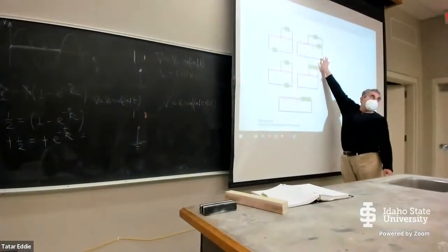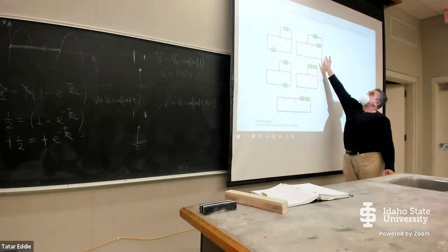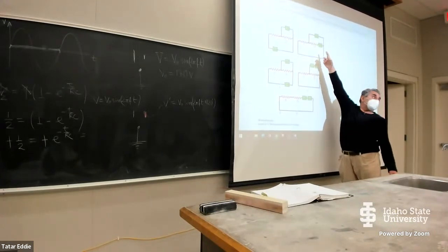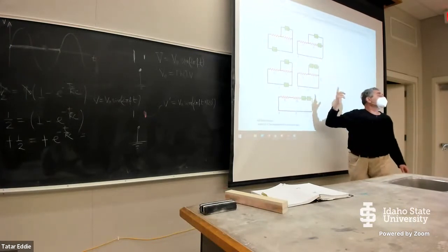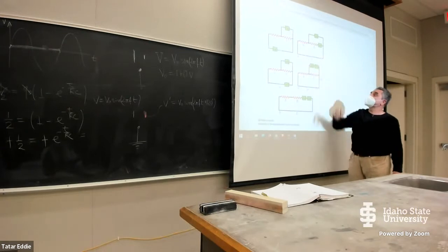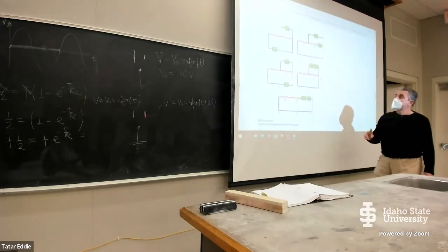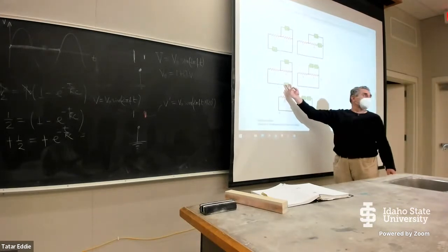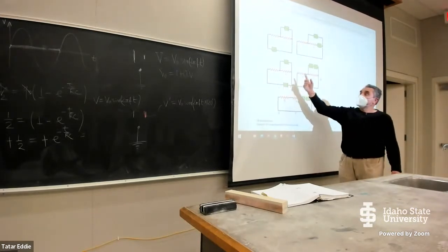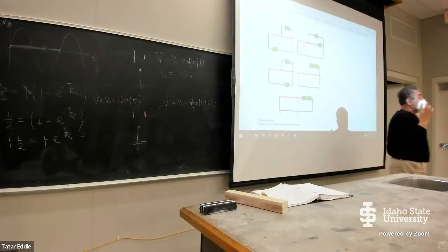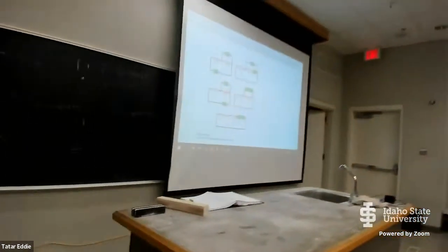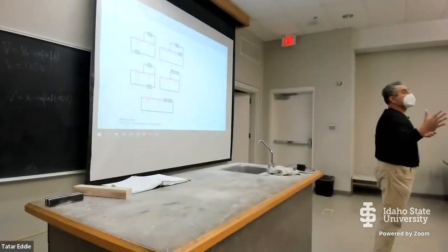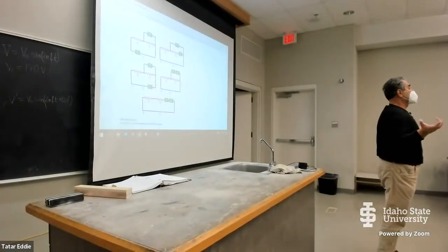The second one is not, because the voltmeter has to be in parallel with R2 and the ammeter has to be in series with R2, and here it is the opposite way. The third connection is also meaningless. By the way, a good ammeter has to have infinitely small resistance in order not to affect the current that it's measuring. The current has to flow through this ammeter without much resistance.